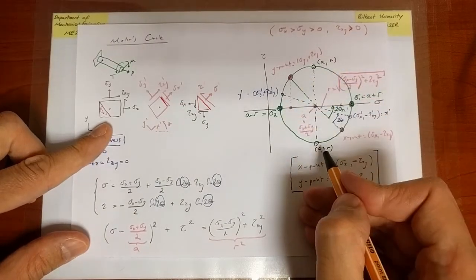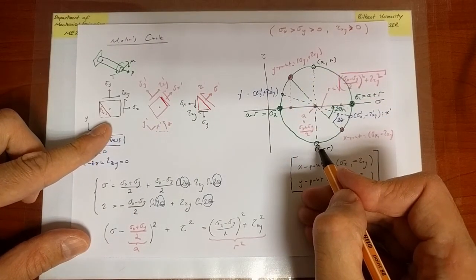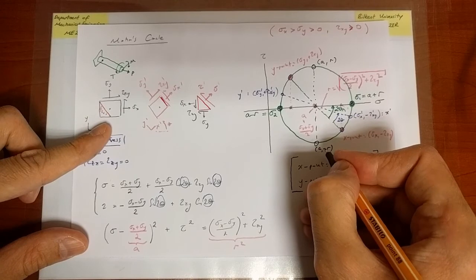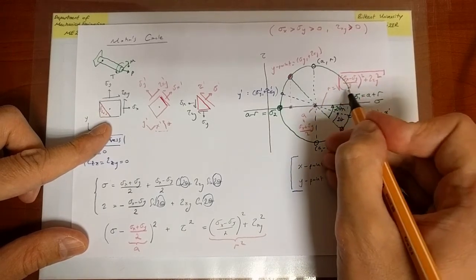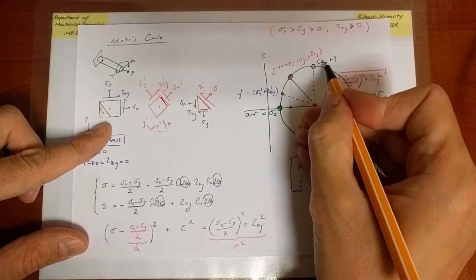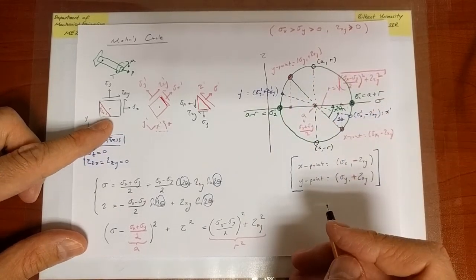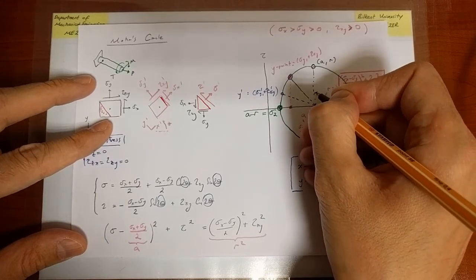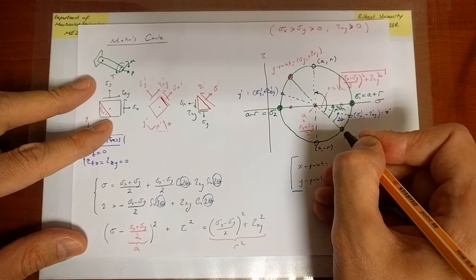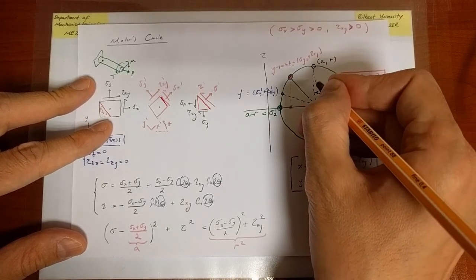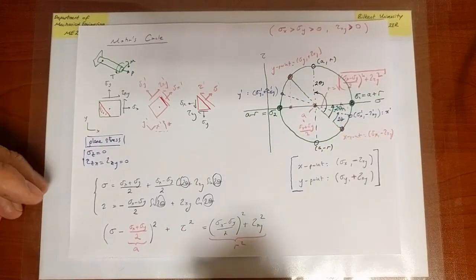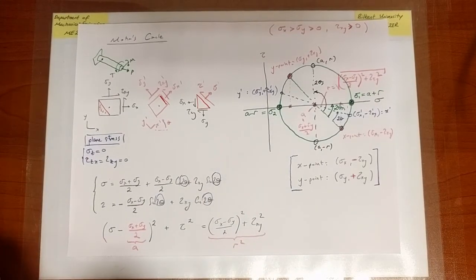And I know that on the plane with maximum shear stress, principal shear stress, I have a plus and a minus value for the shear stress, which is equal to exactly this value, plus minus that, and the normal stresses are the same, and they are both equal to A, as they should be, right? So everything is aligning, so this angle over here is equal to rotating from the original picture 2 theta n plus twice as much, 90, or 2 theta s, right? Theta s and theta n differ by 45 degrees, takes me to the maximum planes with principal shear stresses.